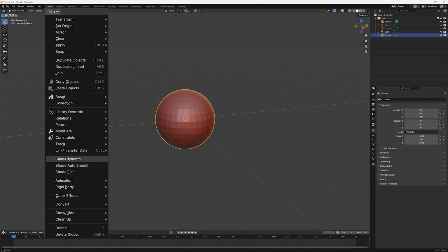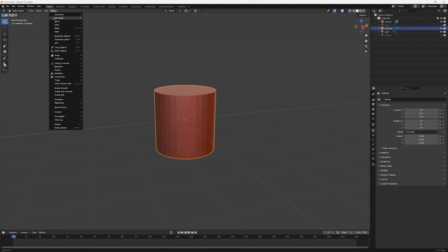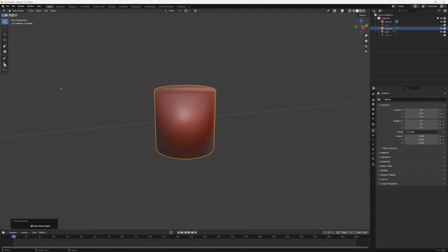Shade Smooth is designed to adjust the shading on curved objects to make the flatness of the faces that make up the shape less obvious and hence create a more realistic curve, but without adding any more faces to the mesh. However, although this option may work well on a sphere, it has trouble when applied to a cylinder or cone, since it tries to create a curve effect over faces that are meant to appear flat, such as the top and bottom of the cylinder.